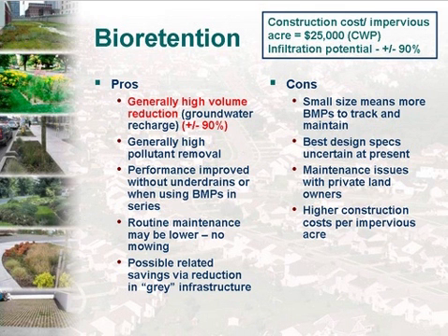Yeah, and another dimension to this whole cost thing, which is such an interesting topic, is site costs too. If you are using more of these infiltrating type devices, and the last bullet on the left there mentions this, you may have some associated cost savings through not having to put in curbs, for instance, or having less of the gray traditional infrastructure. So you may end up with some substantial cost savings there, which would maybe offset the actual installation cost of the particular BMP. We have in the resources list available to all our listeners a new document that EPA just came out with a couple weeks ago on the costs at the site level using a low-impact design versus the conventional design. And I think almost all those case studies show a significant decrease in your overall costs as well.